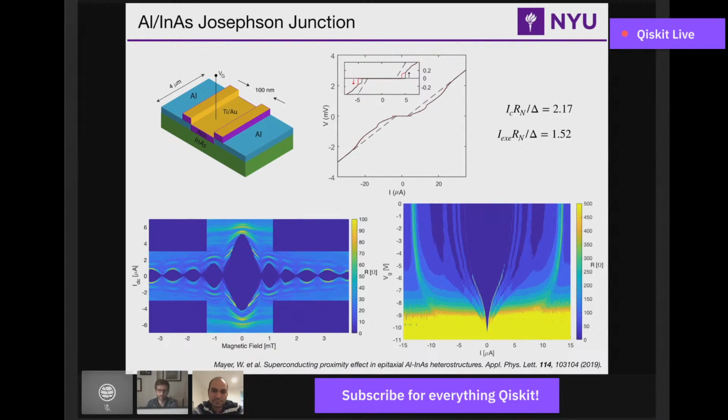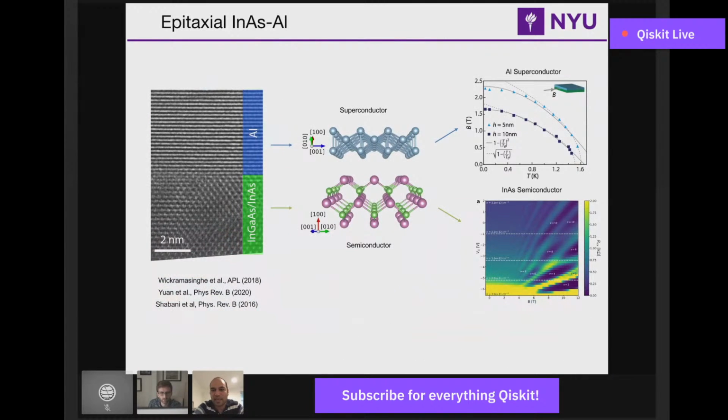I see, and it doesn't seem to damage or increase the roughness of the surface or any of this stuff. It doesn't do that. You get a slightly, like 5 to 10% increase in the density of indium arsenide channels. So something happens at that interface. It's not perfect, but it's not substantially different. When I look at the Shubnikov-de Haas, lower right, I can measure the density, right?